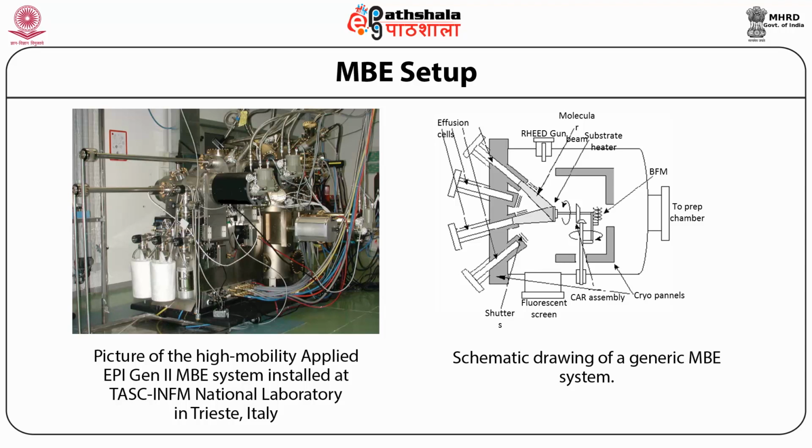Now, molecular beam epitaxy has several key characteristics which make it an industry and research standard growth system. It is a versatile technique, that is, it is used to make epitaxially grown films, and abrupt doping profiles such as delta doping, commonly found in high-speed semiconductors, can be synthesized.